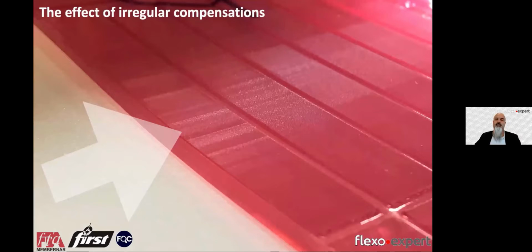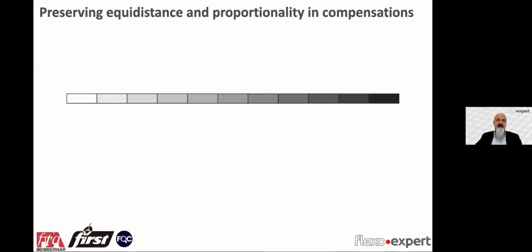The result of one unsmooth or irregular compensation is a plate that will definitely print unsmooth and irregular tone transitions, especially when we have vignettes fading to zero. And you can see it already on the plate. Try to take a backlit look at the surface of your compensated plate and you can judge yourself. Just take a look at the vignette fading to zero. If you see a movement in those tones, there might be something that could affect printing in a negative way.